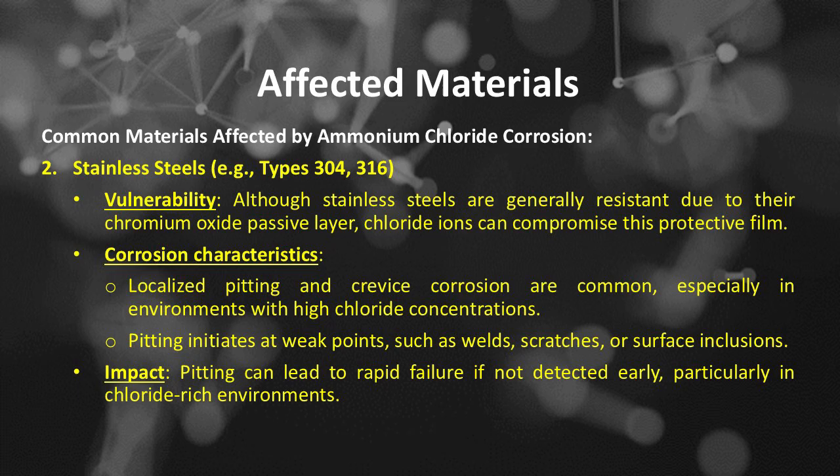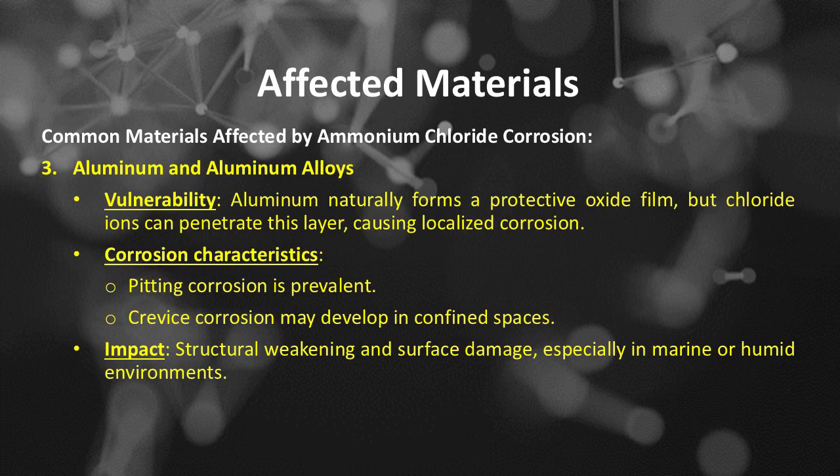Pitting initiates at weak points, such as welds, scratches, or surface inclusions. The impact of ammonium chloride corrosion on stainless steels: pitting can lead to rapid failure if not detected early, particularly in chloride-rich environments. Number 3 of the common materials affected by ammonium chloride corrosion is aluminum and aluminum alloys,